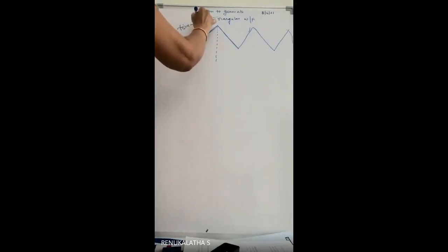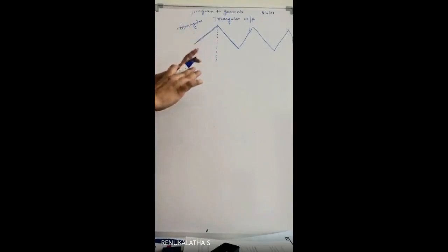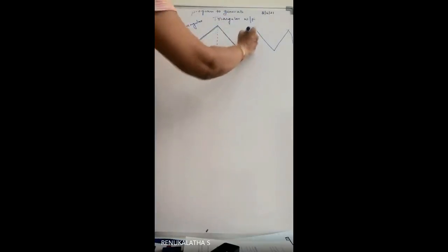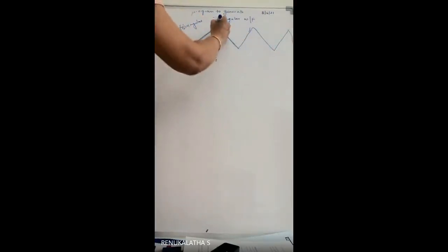See the shape difference. Previously, the data sent to the DAC was logic zeros for some time and logic ones for some time. In between sending logic zeros and ones, we called it delay. That would generate a square waveform. Now we need to generate a triangular waveform like this. That means you need to send suitable data to generate this part of the waveform.